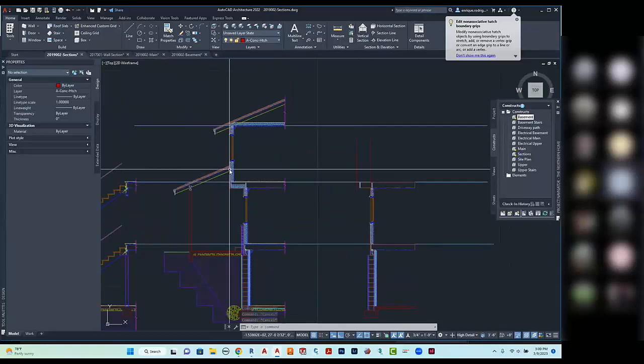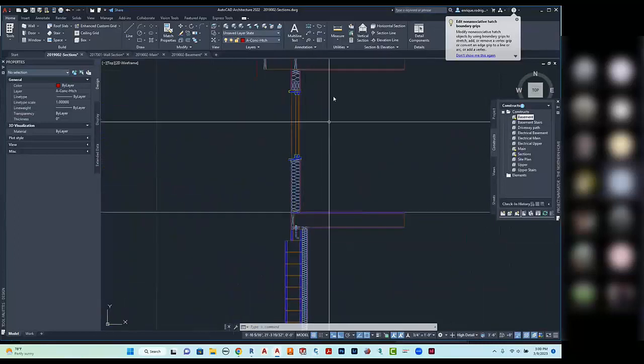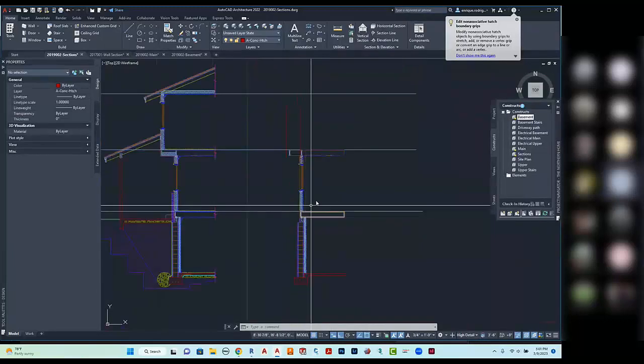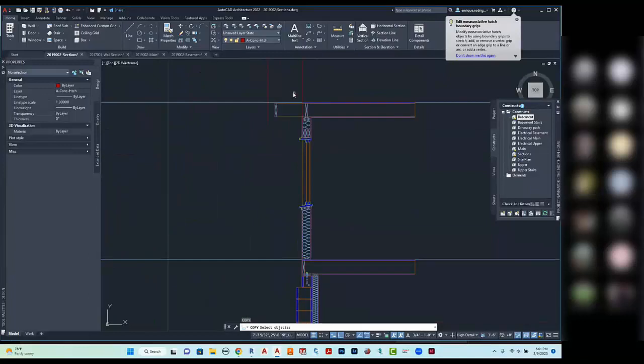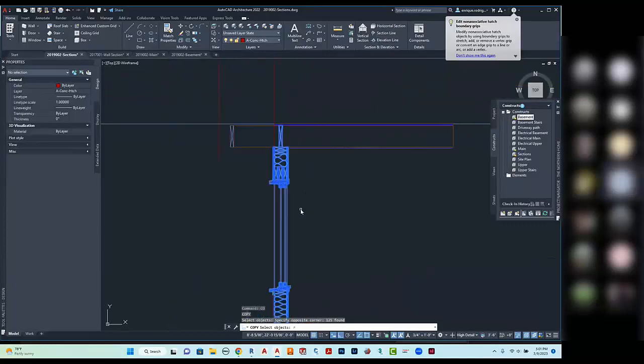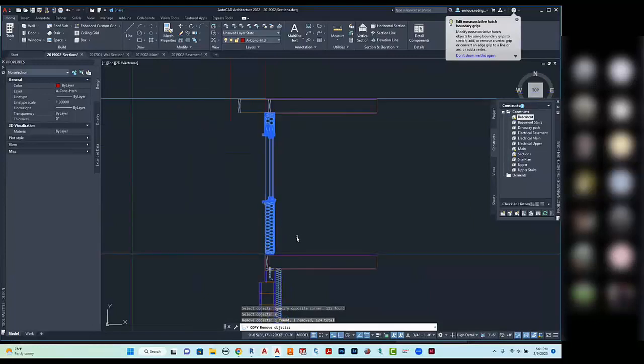We've got a similar condition with our wall located all the way up. Again, it's also an 8'2". No sense in redrawing all of this. So let's go ahead and copy. I'll take all of these elements right in here. I'm going to remove some of them, I don't need the blocking, but I do need everything else that I've drawn in here.